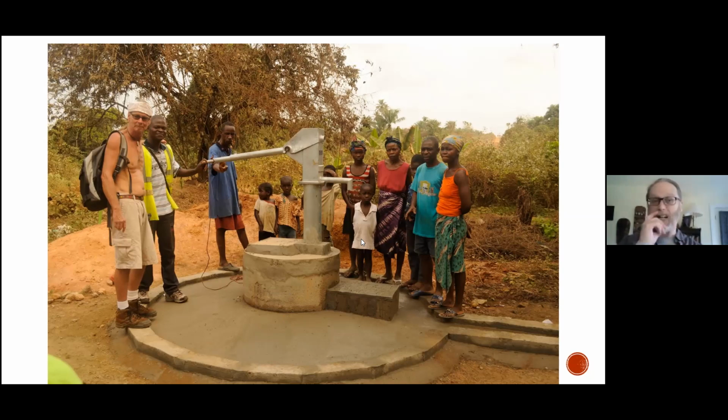And so what it does is basically guarantees that the water coming into the vessels that these people are filling up will be clean. Less chance of contamination. But it is a fixed amount. When we talk about pumps and even water meters, we're going to talk about positive displacement. And that's what this is. Every plunger stroke goes down below the water table and then pulls back a fixed volume of water.